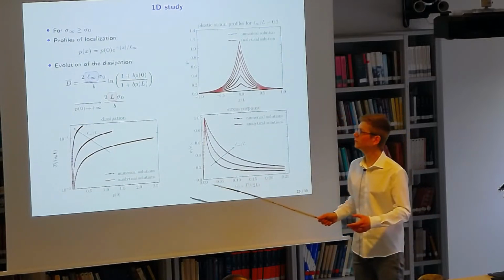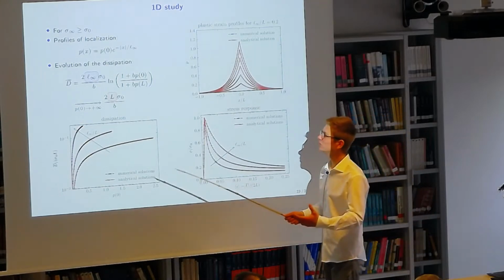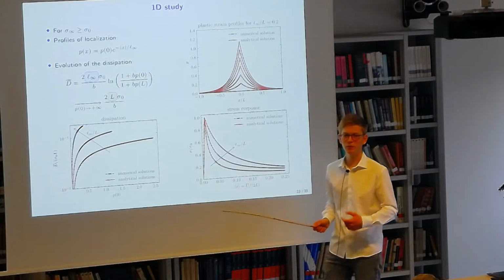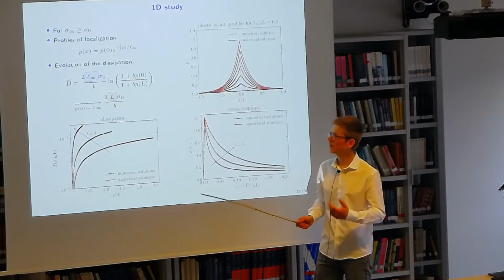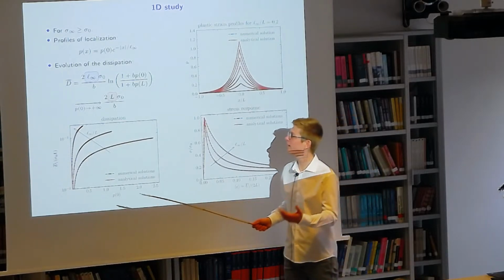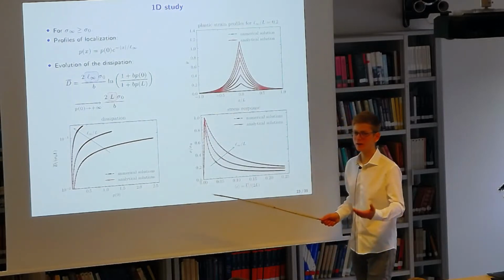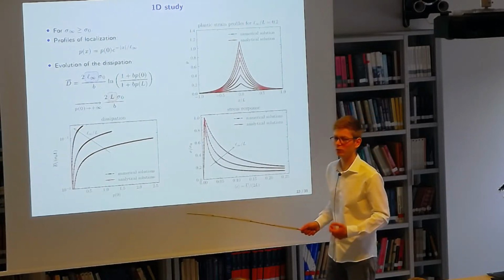It's quite interesting because in a way, it reminds us that this regularization approach for plasticity is not quite the same as regularization of damage, in which we could expect that the final dissipation would involve one length-like parameter, for instance, which would act like a regularization one.